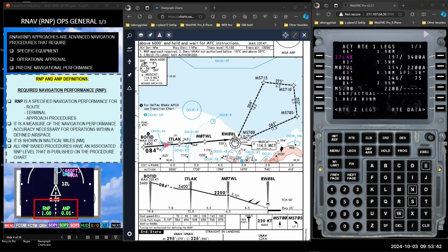So that's important to realize that when the temperature is away from standard on the cold side, we make corrections so that we're safe. But on the warm side, we do not make corrections, but we have to expect that we will be high when we go visual, when we decide to land. And how high? It's all based on the formula that's used for temperature corrections. All right, and I've talked about that in videos and actually pointed out what that formula is.